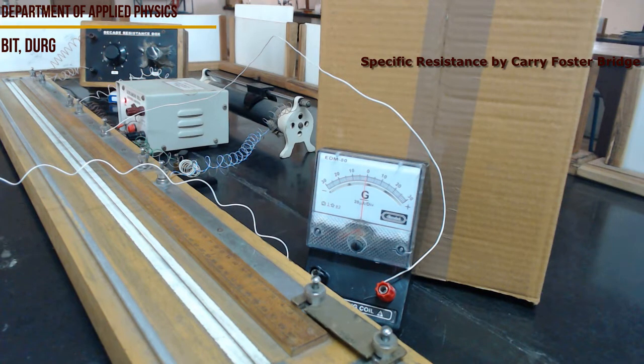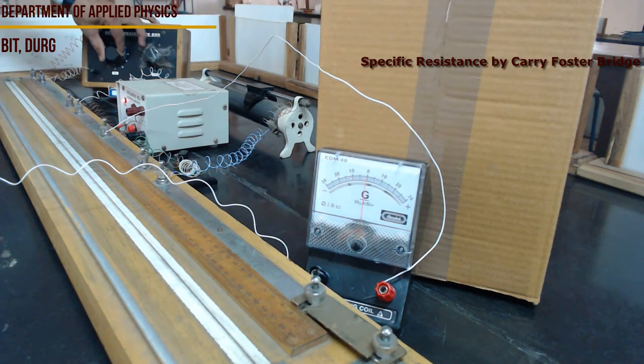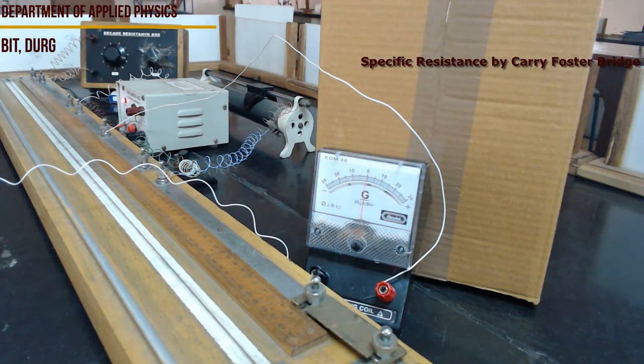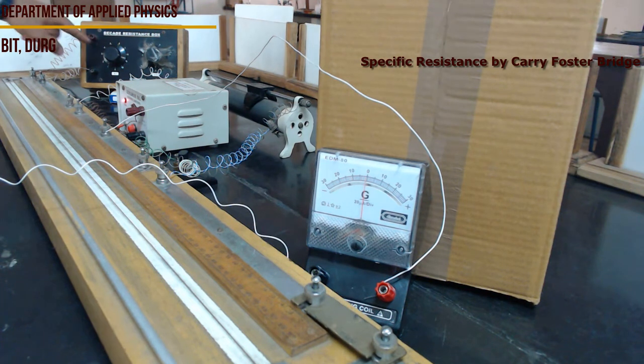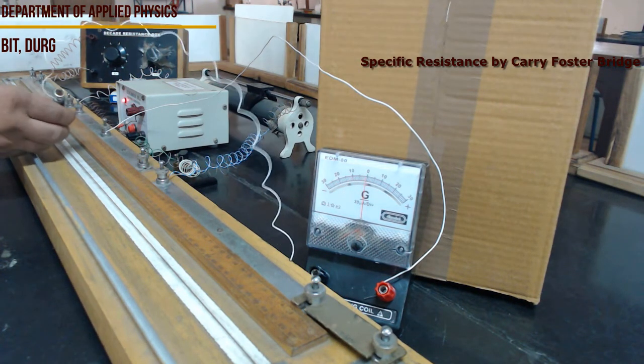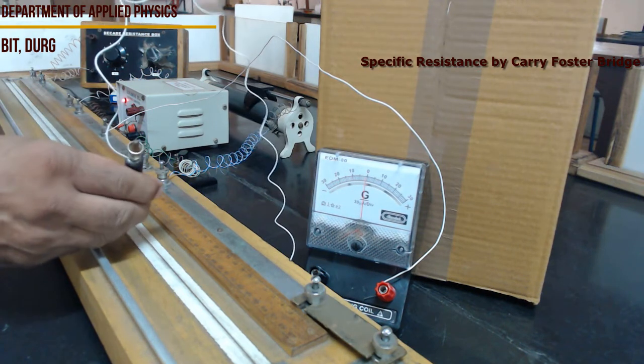Now what do we do? After this, we apply a definite resistance of say 0.1 ohm with the help of this RB resistance box. Initially it was at 0. Now I have kept this resistance, across these two terminals there is a resistance appearing, and the value of the resistance is 0.1 ohm. Now I have to find the position of the null point.